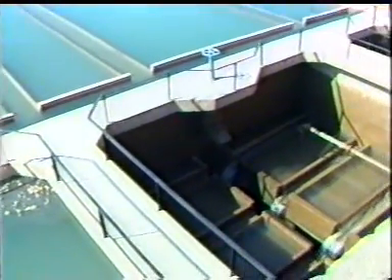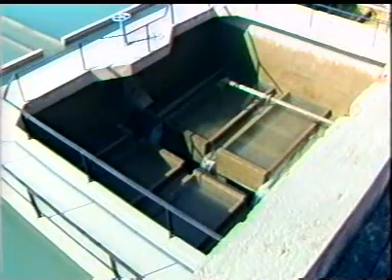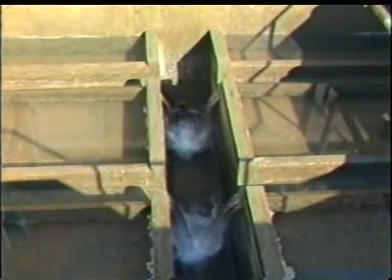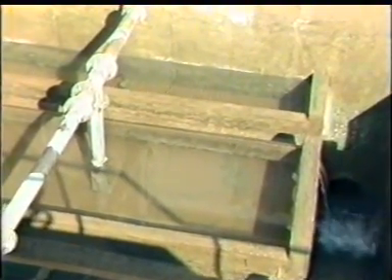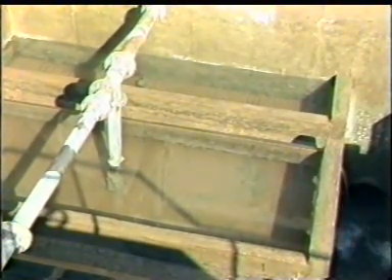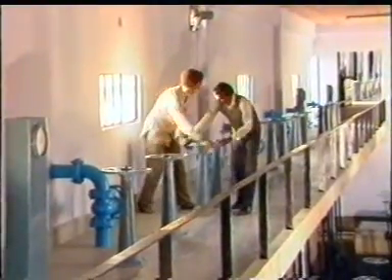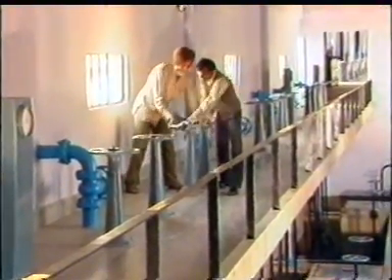The process of backwashing should be continued till all the impurities flow out. This can be judged from the crystal clear water coming up through the filter beds. Different controls are provided for backwashing and controlling the outflow.